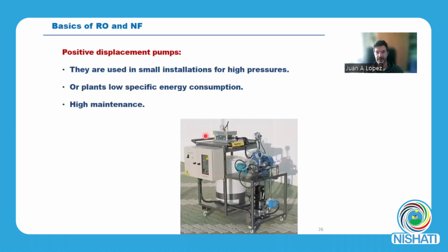for instance, this is my smallest desalination plant. Here we put the membrane in this small container, and this is my desalination plant. So I can work up to 70 bars. We use small pieces of membranes, so we can make a demonstration, or we can make a test for the selection of the best membranes, or for washing the membranes.